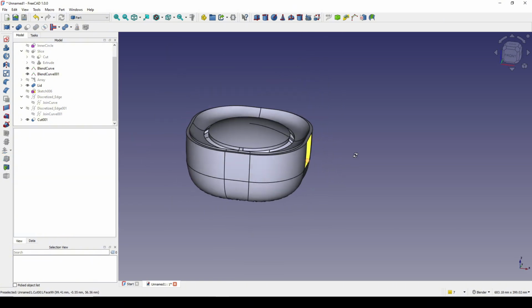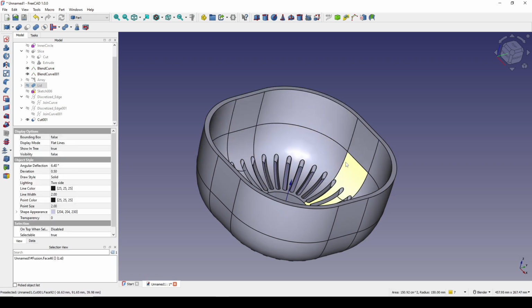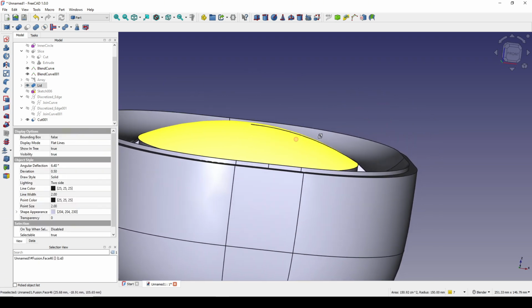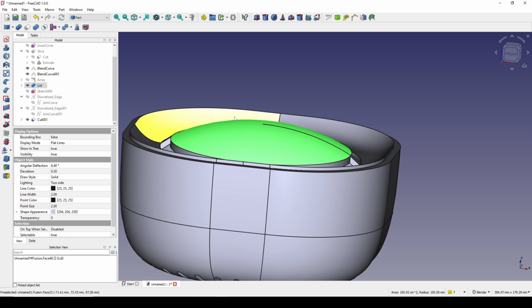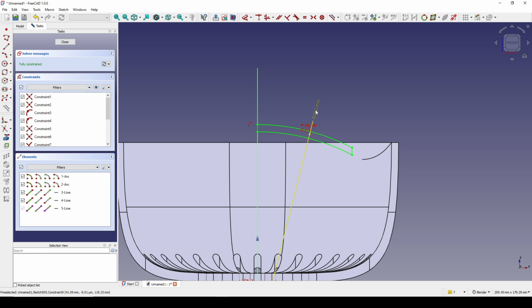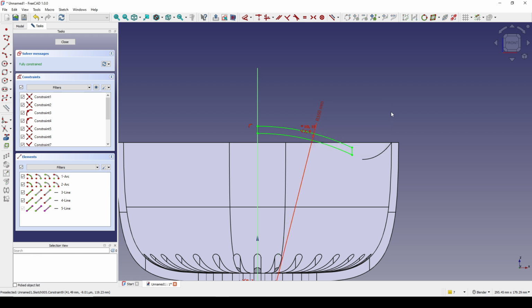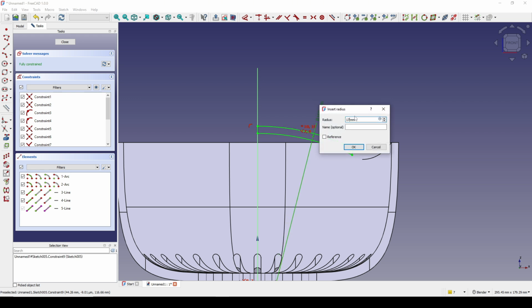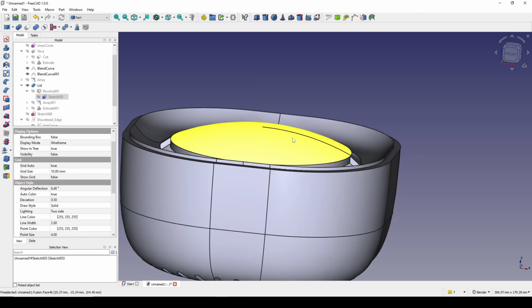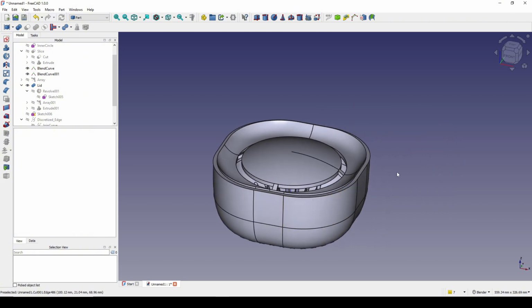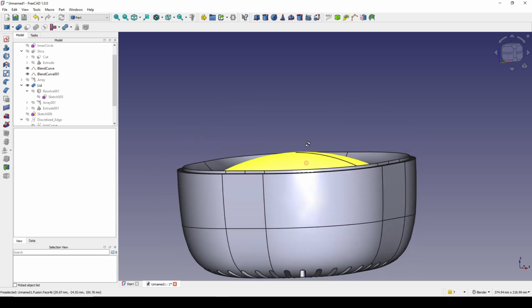Okay. So this is the result that we have, the lid and the body. So maybe I should change this one a little bit lower. Let me go to delete. And let's go inside here, the revolve 001 and this cut 005. Let's change this one to 160 or 170. Close. Yeah. Yeah, I think 170 is better.